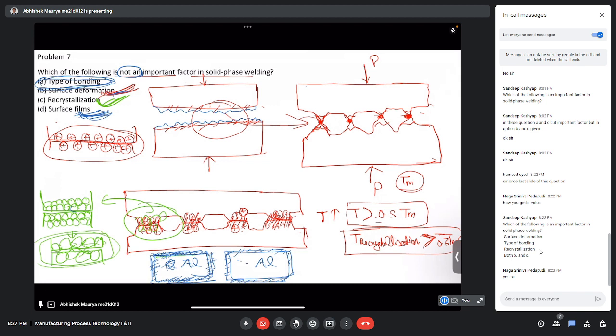I told you that if you closely look at the surface, there is only point contact between the surfaces, between the peaks. But when you apply some load, these points get deformed, and this peak will get converted into something like this because of plastic deformation. The material which is here will flow here, and it will finally deform into something like this.